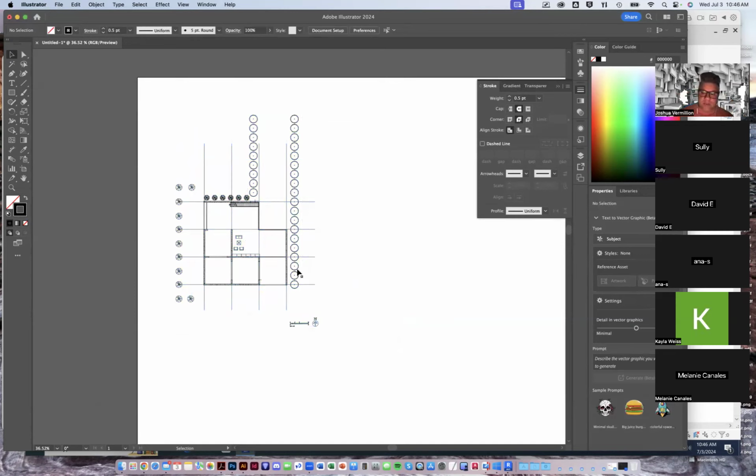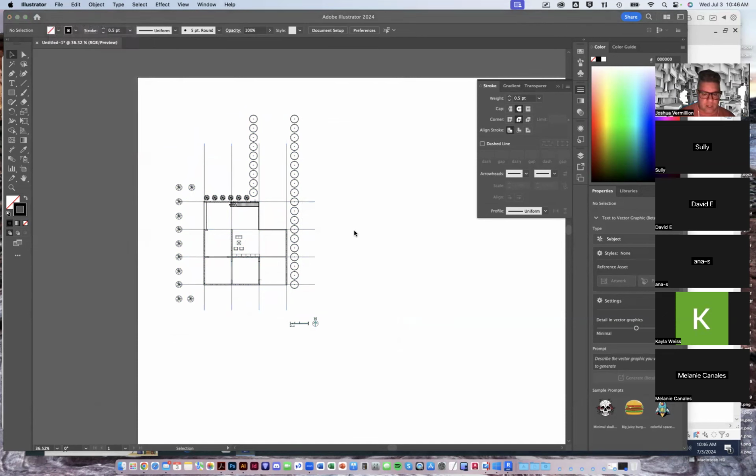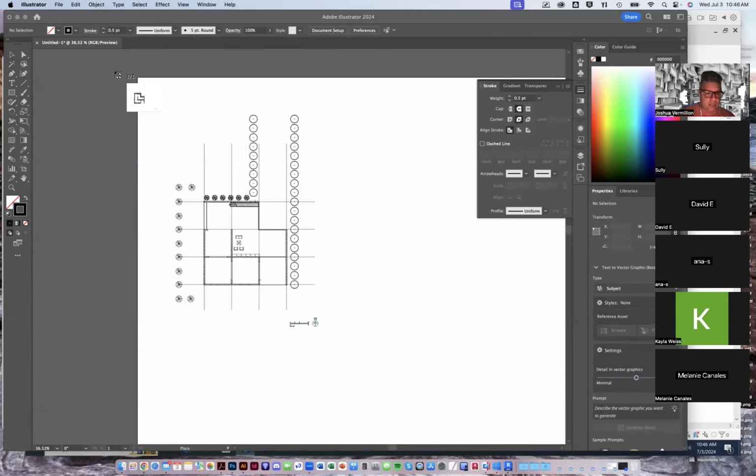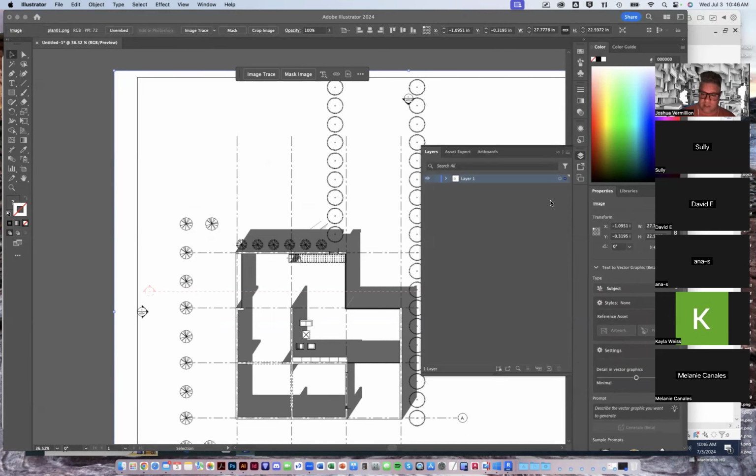All right, so here we go. There's nothing stopping us from also placing that PNG file and seeing what we have there. Let's see, there it is, plan.png. I'm going to go ahead and place it. It might be really large or really small, I don't know. And again, if I go over to the right-hand side, you see these 2 sheets layered on top of each other? That's a layers box. If I want to create a new layer, I go down to the bottom and click create new layer with a plus sign. I'm just going to drag this new layer, layer 2, down. I click and drag it. The order the layers are in is the order they show as overlays on screen, right?